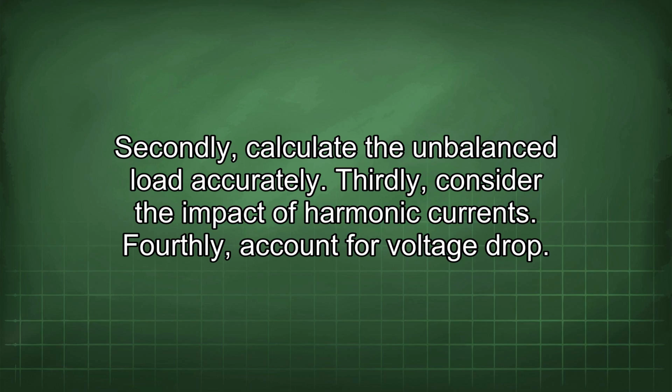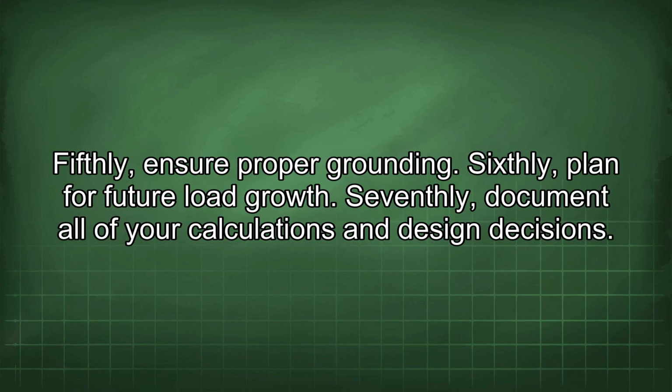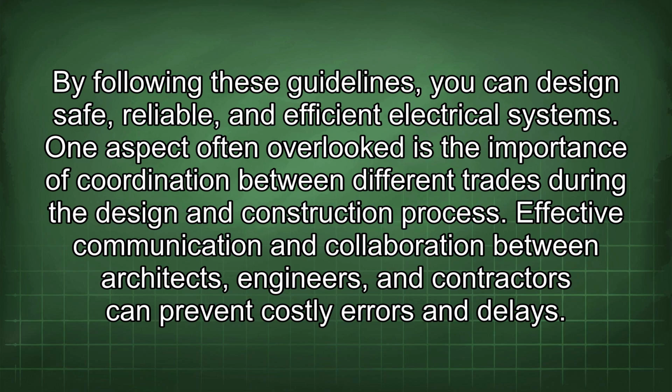Fourthly, account for voltage drop. Fifthly, ensure proper grounding. Sixthly, plan for future load growth. Seventhly, document all of your calculations and design decisions. By following these guidelines, you can design safe, reliable, and efficient electrical systems.